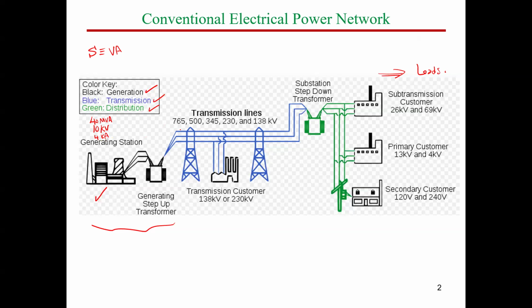Once we reduce the current from 4K to 0.4K, you know that any power loss means I square times R. R is nothing but the resistance of the transmission line, the cables that we use to transfer the power. And I square is the square of our line current. Since you already stepped down the current, the value of I square R would be less.